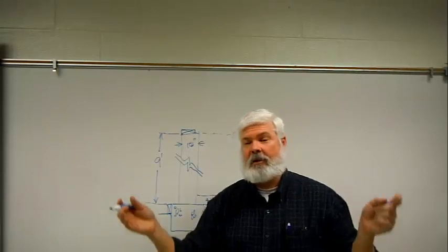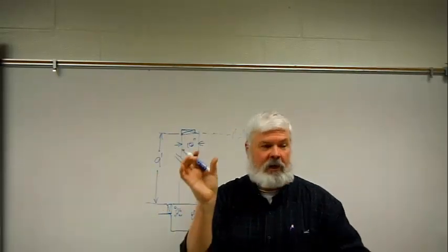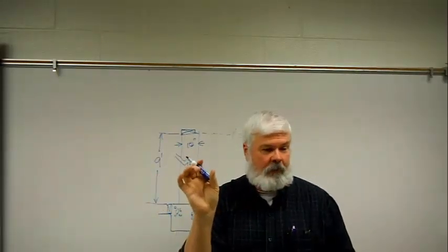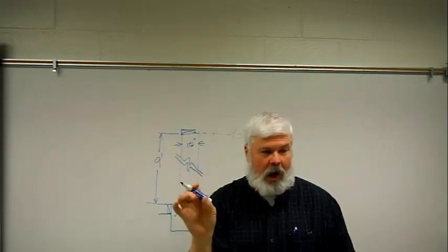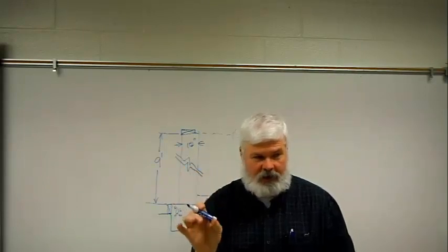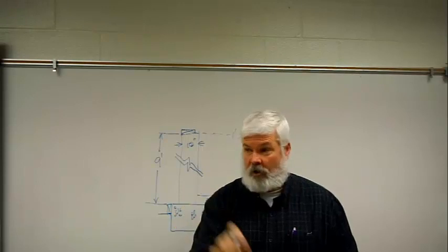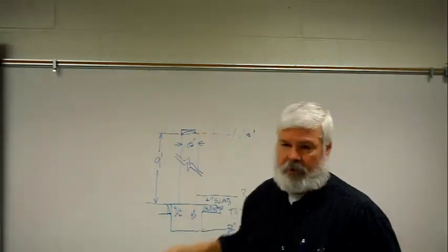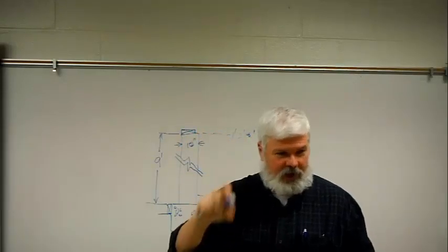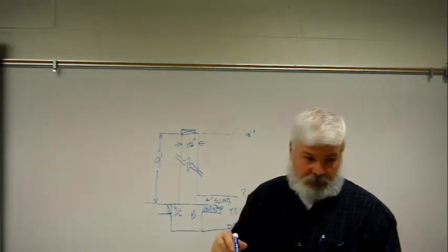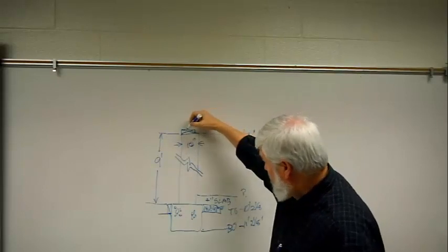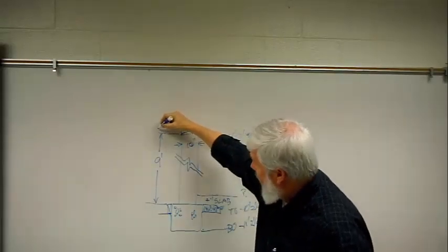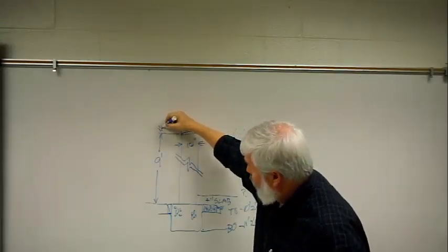It is because the lumber shrinks, and the kerf that the big saw blades in the mill are wide, and there's a lot of kerf. There's a lot of sawdust produced, and the lumber also shrinks. That may be totally wrong, but it is what it is. It's 1.5 inches thick, and that's my excuse for it, and I'm sticking with it. So we've got 1.5 inches here of sill plate.